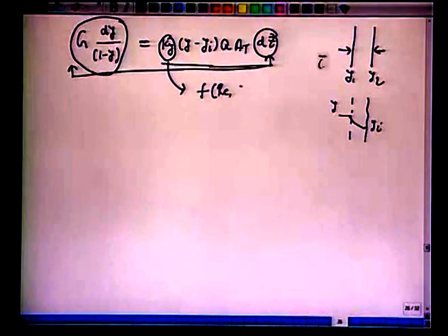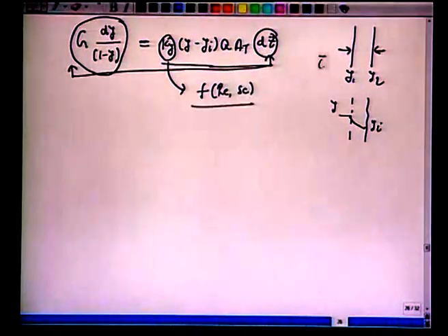Okay. So, whatever change in the gas phase has been balanced, made equal to this mole flux multiplied by the cross sectional area. We have introduced this Ky, not an unknown quantity. We have earlier said that Ky should be calculated from the operating conditions, knowing Reynolds number and Schmidt number.